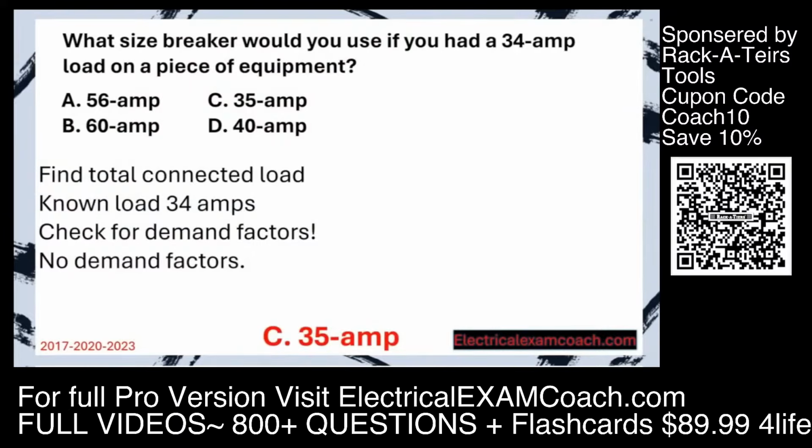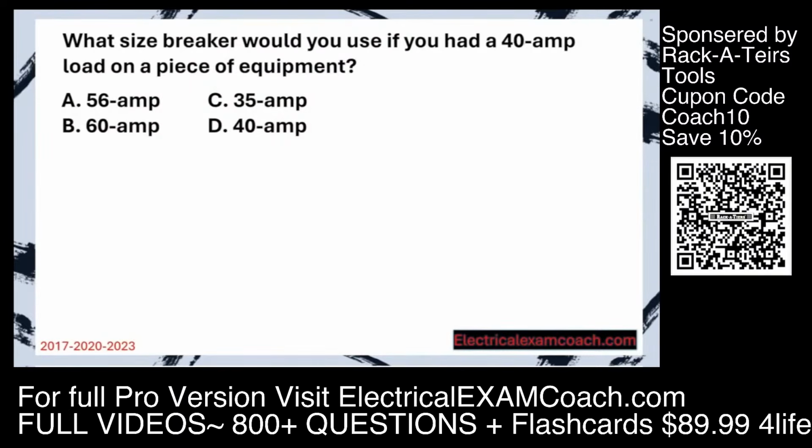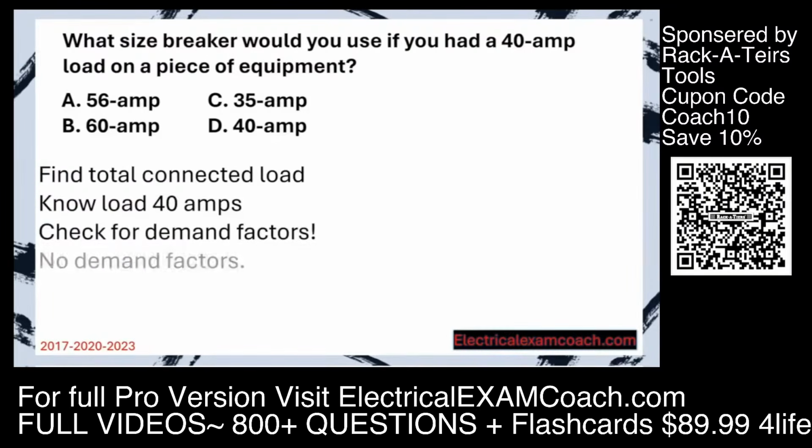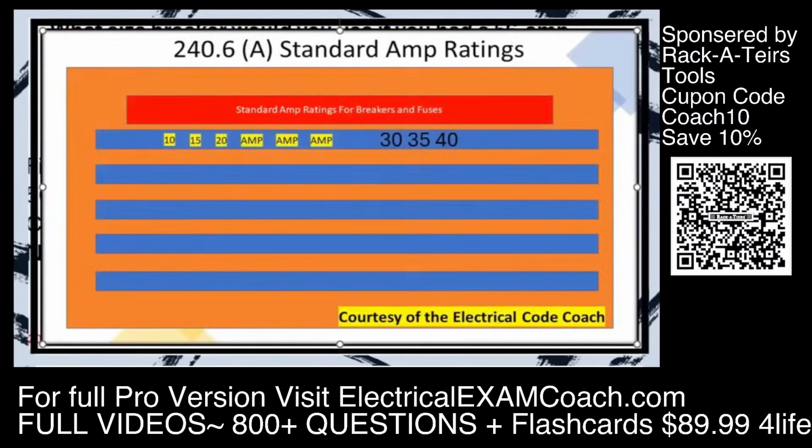Let's get to it. What size breaker would you use if you had a 40 amp load on a piece of equipment? Step 1, find the total connected load. The known load right now is 40 amps, but we check for demand factors. And in this case, there are no continuous loads or specific piece of equipment. Therefore, there are no demand factors. We're going to head to table 240.6(A).